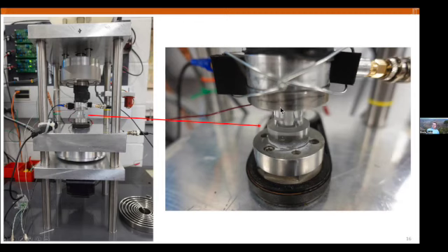which allows us to measure the rotation of the bottom sample. The top sample instead is locked and is attached to a torque cell and a load cell. The torque cell is needed to measure the torque and eventually infer the shear stress, and the load cell is needed to calculate the normal stress and the normal force. In here you also see other details that I'm going to show in another slide. Fundamentally, the fault that we are looking at is the contact between this top sample, which doesn't spin, and this bottom sample, which does spin.